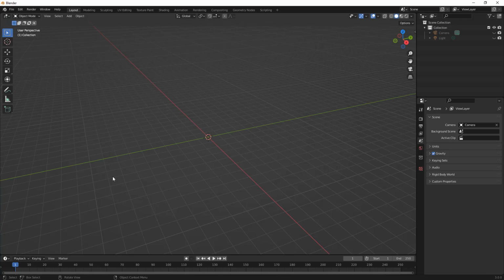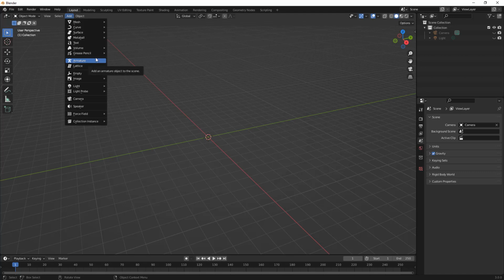Now in Blender, it's very similar to Fusion 360 where we can add primitives, and there are of course other ways in which we can define certain objects. But I want to start by adding a new primitive. This can be done by going to Add and picking one of the ones that we want. We have looked at this a little bit in the past in one of my videos where we talked about adding or creating subdivisions and exporting and remeshing. But in this video, we're going to start from scratch, and talk about a couple of the most common things that we would do in Blender.